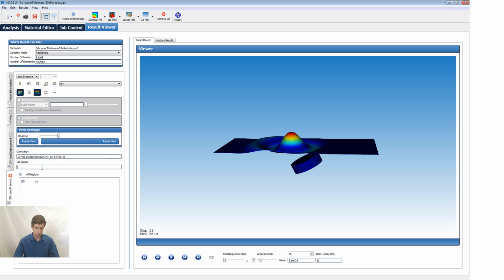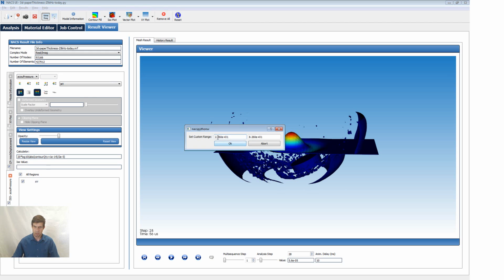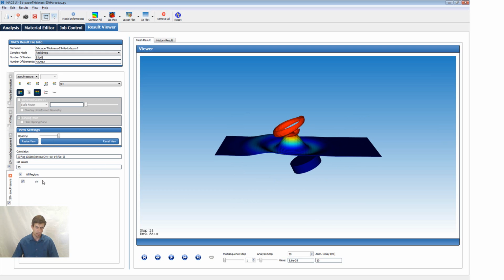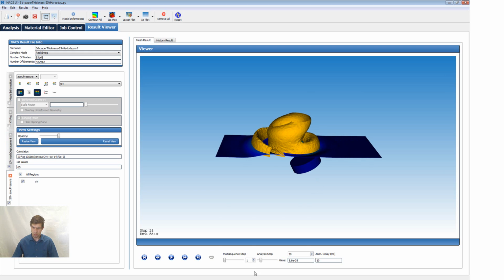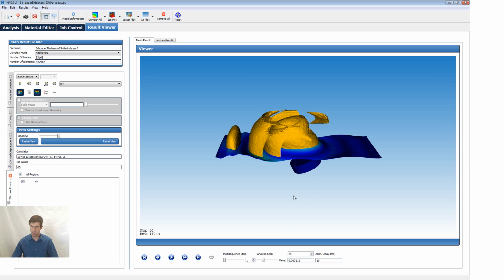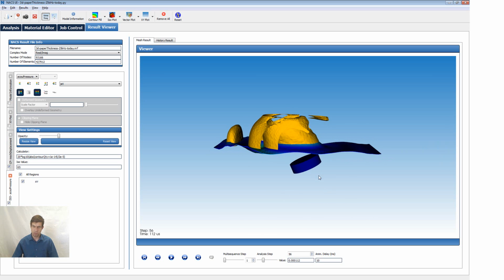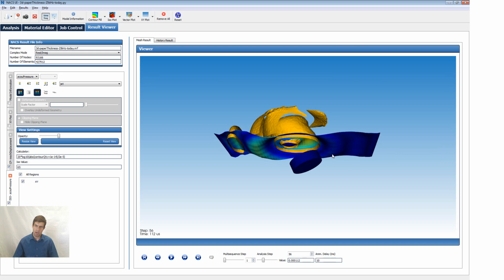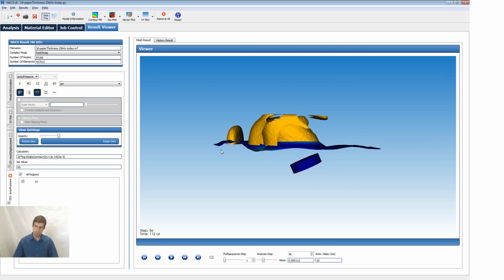Right now we want to obtain some isometric surfaces. Our range is currently between 22 and 82, so let's see what happens at something around, let's say, 75 dB. Not too much, let's get a little less, still not too much. So here at 65 dB, yeah, that looks like we can see what happens in the acoustical domain. Now only on the upper half, of course, due to the paper in between, we've got a double impedance step, and that means that the acoustic sound pressure levels will be much less on the lower half.